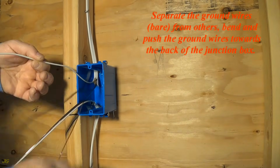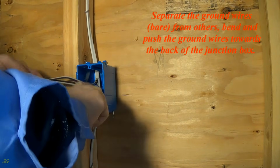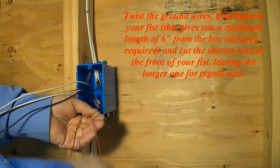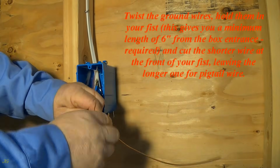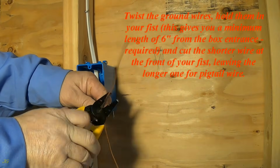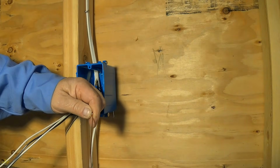Separate the ground wires, bare, from others. Bend and push the ground wires towards the back of the junction box. Twist the ground wires. Hold them in your fist. This gives you a minimum length of 6 inches from the box entrance, required, and cut the shorter wire at the front of your fist, leaving the longer one for pigtail wire.